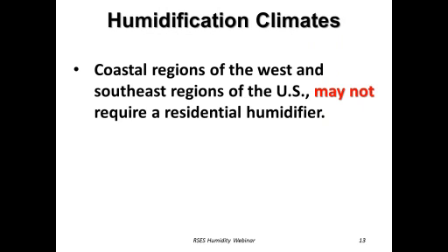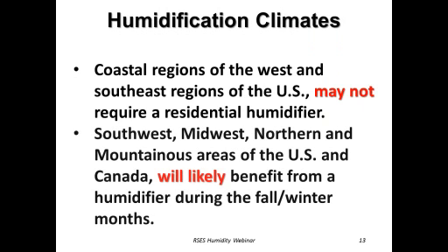Humidification climates. There's basically two climates. One in the U.S. is the west and the southeast regions. They may not require any residential humidifier. There are commercial applications where you need humidifiers pretty much regardless in those areas. Also in the southwest, midwest, northern, and mountainous areas of the U.S. and Canada will likely benefit from a humidifier during the fall and winter months.